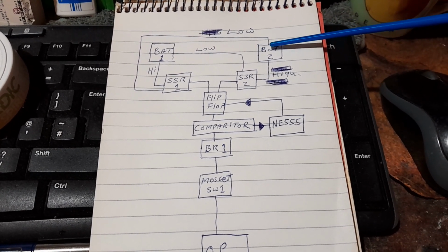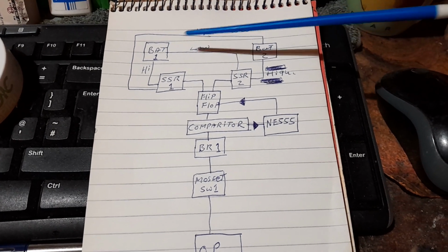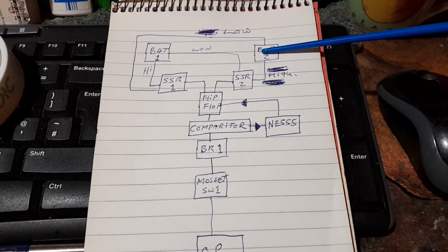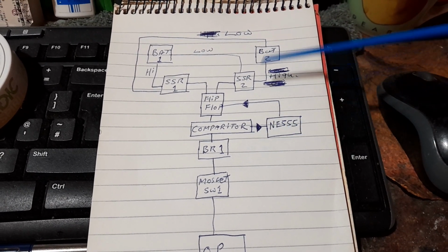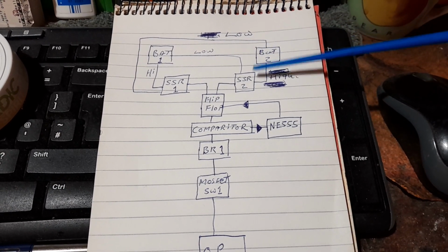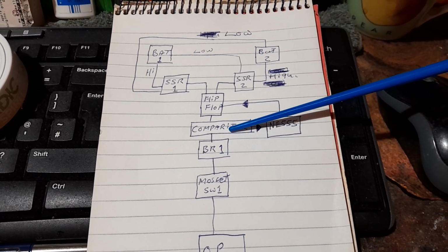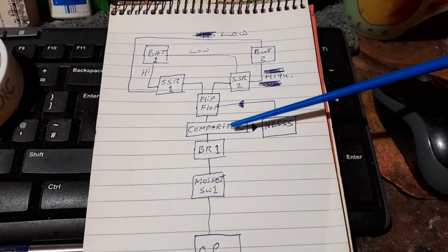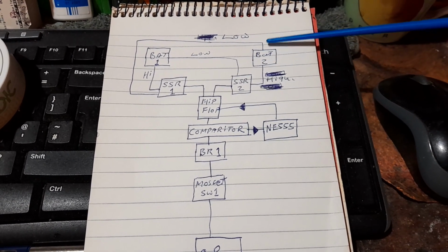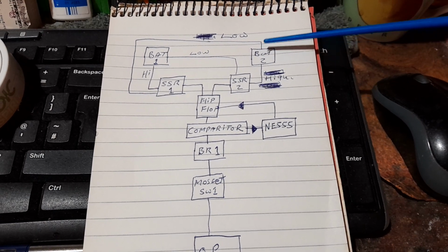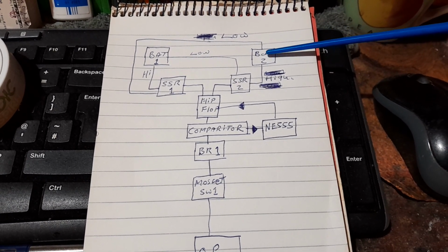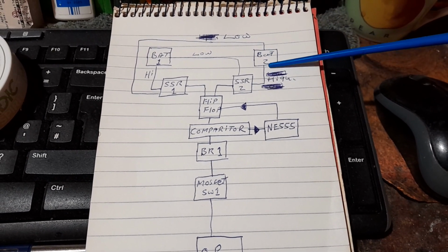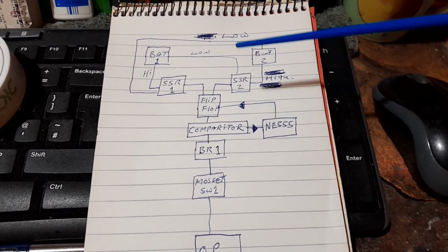So whichever battery is connected in series, we would try to supplement any losses by sending that energy back to the high side, because it's pointless sending it to the low side. All you're going to do is detract from the output of the high side, because as the low side starts to increase in voltage, the high side has a bigger voltage drop across the low side. So we actually subtract energy efficiency that way. It makes more sense to send power to the high side, because by doing that we're actually charging the low side at the same time.